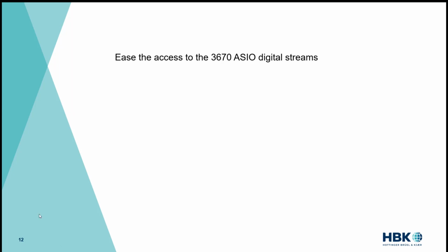The second principle is calibrated DSP. And what do I mean by that? We're well aware that DSP tools are available everywhere, and you can process an FFT with even Excel, for example. But what you get is a raw complex spectrum, and what you need is typically magnitude and phase.